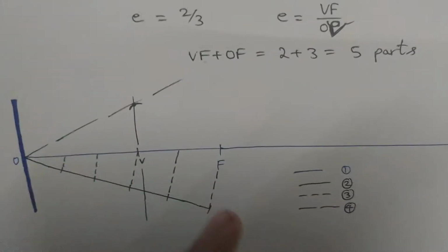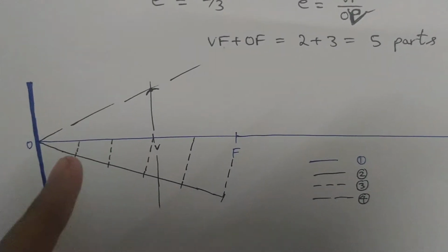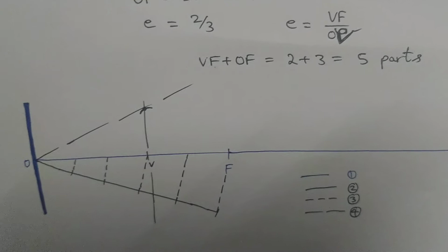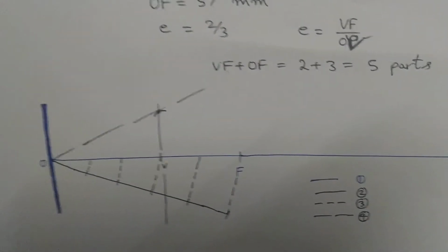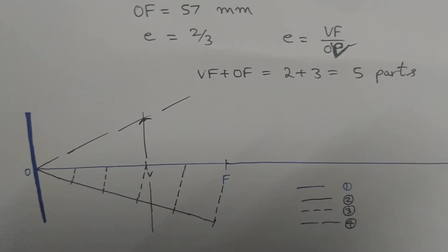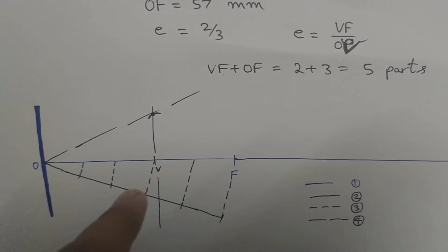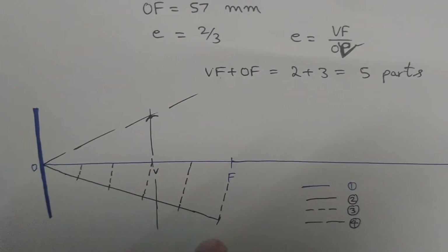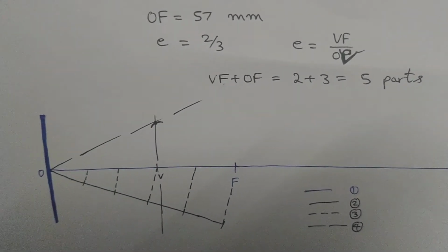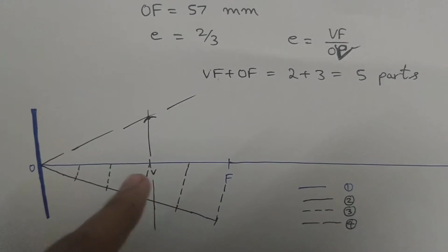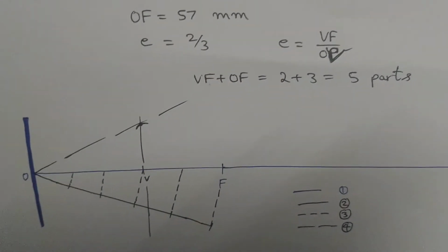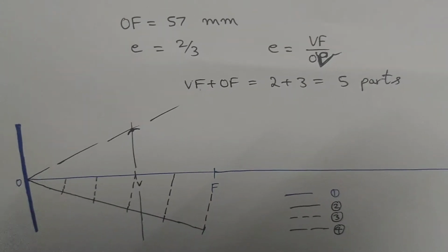Step 3. My last point on the extended line, I'm going to connect it with my focus. After that, I'm going to use my drafter and connect all the points on the extended line with the axis, making sure that each and every one of these connected lines are parallel. This is my step 3.